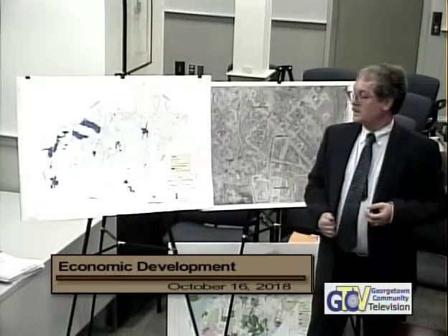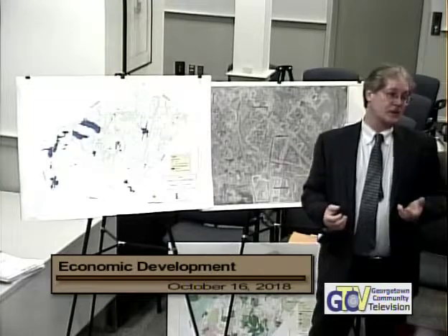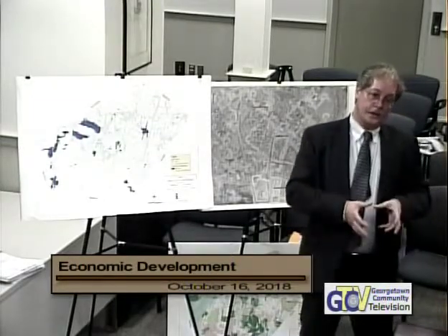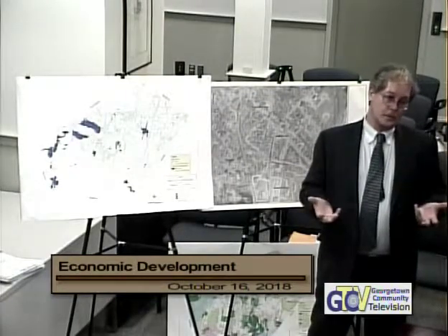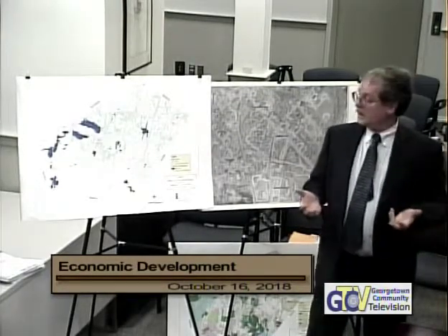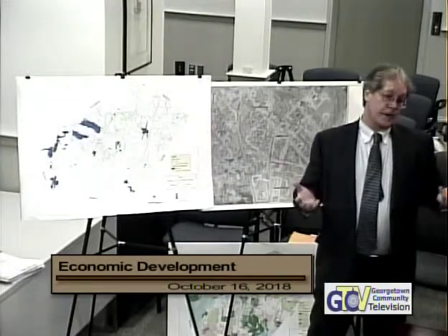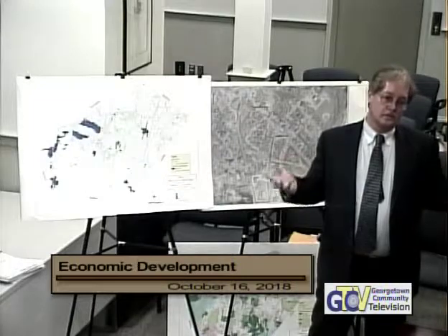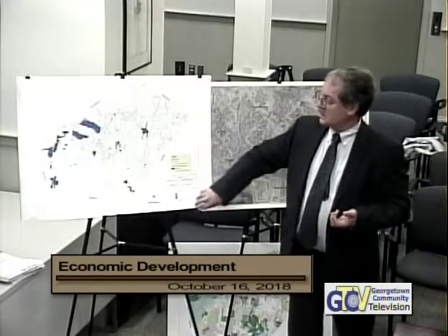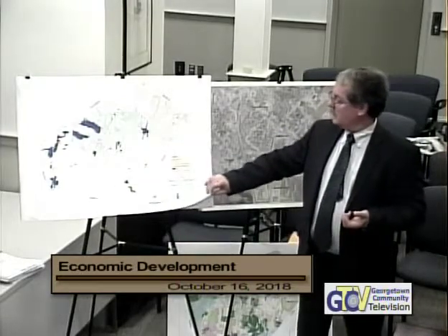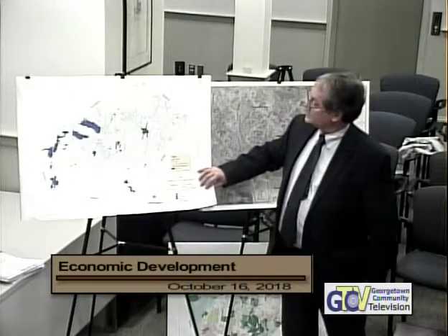So the typical solution nowadays is a decentralized alternative, and that's basically to take the wastewater, treat it locally, and then infiltrate it into the ground through a subsurface disposal system of some type. The biggest challenge for us on a local alternative is trying to find an area where we could do that. So we used MassGIS information for a lot of the base information, or desktop evaluation, of those lots.